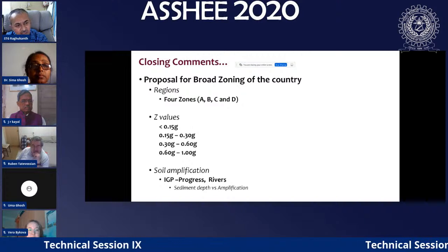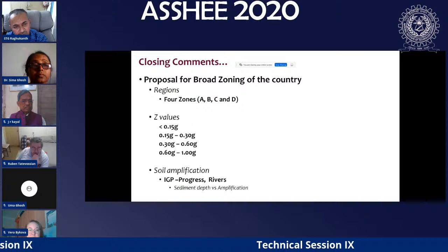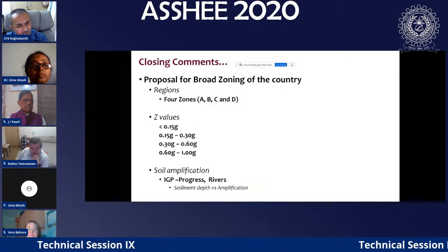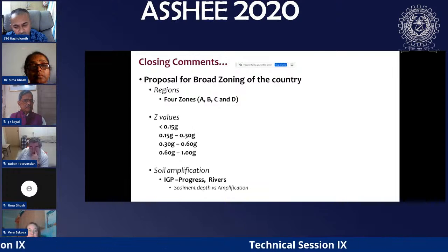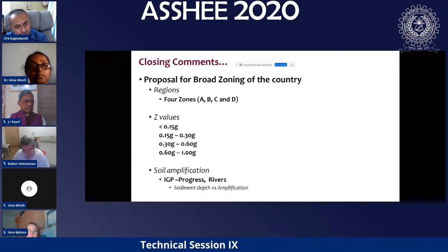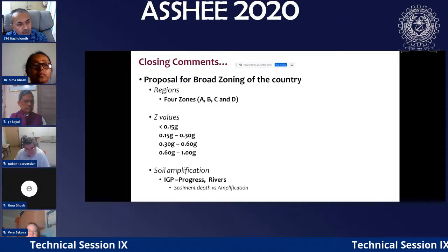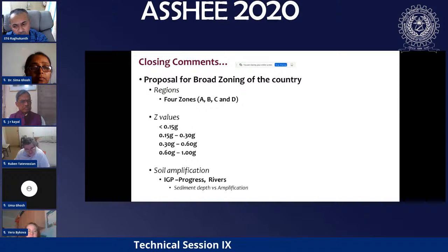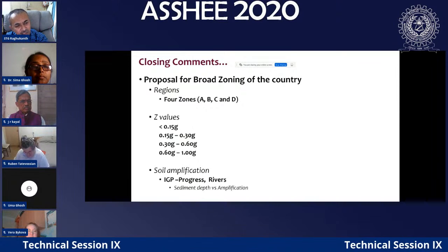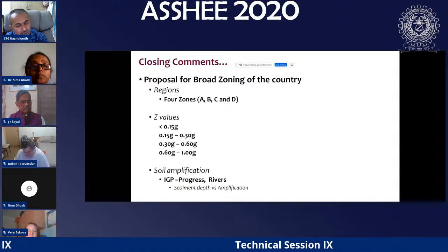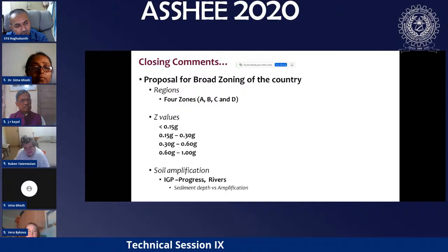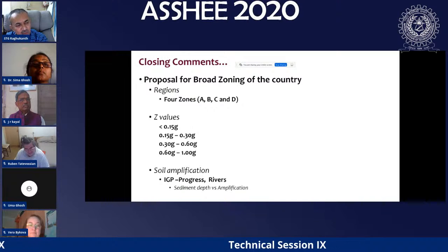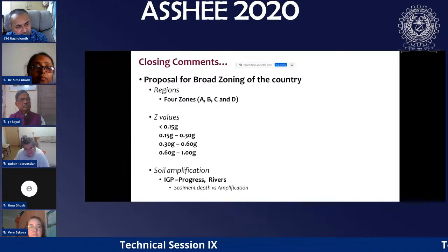So finally we will be having the hazard maps also, but as I already mentioned, the practicing engineers of our country still want to go ahead with zones, like 4 zones or 5 zones, and then give this value, because there are some practical difficulties. Like if in a city I give one street one value and another street another value, we will have a lot of problems. So for that, this zone map has been prepared. So 4 zones, but these 4 zones have been estimated from the probabilistic seismic hazard contours itself. As I already showed you, we have done fault based, circular smoothing, then elliptical smoothing, but everybody prefers elliptical smoothing, which combines the fault as well as the circular smoothing.